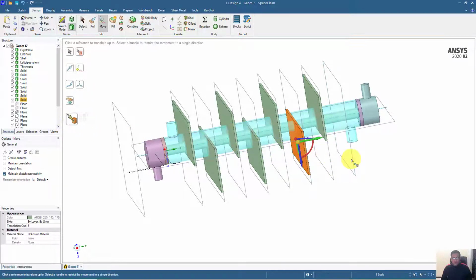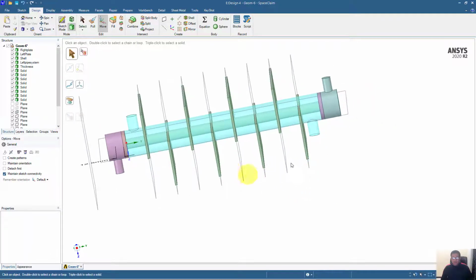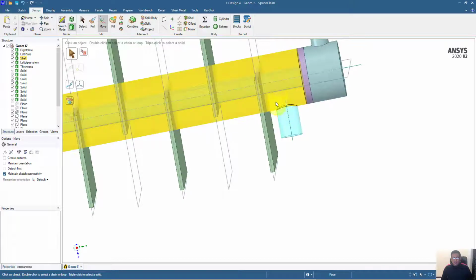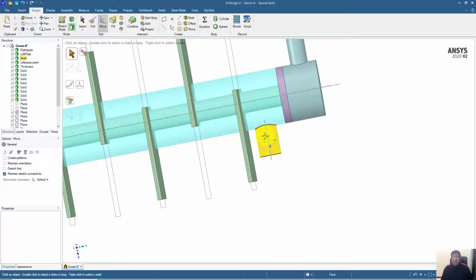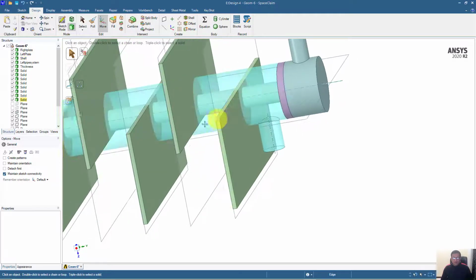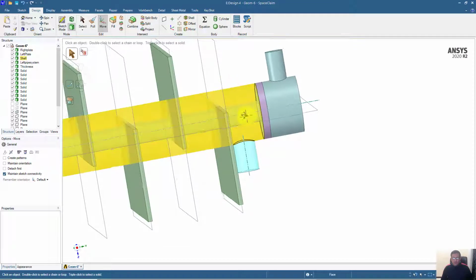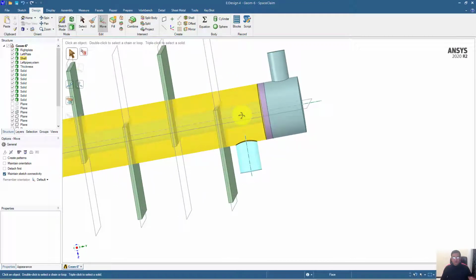Okay, this is very important because if you take a look at this geometry here, this outlet is on the bottom side, so the flow should come in from here and then go upward, so that it can make contact with the flow coming from the tube. In this way we can ensure there is 100% heat transfer between the shell and the tube, and again it will go down from the top side, so again it will interact and be in contact between these two fluids, so this will make the transfer optimal.